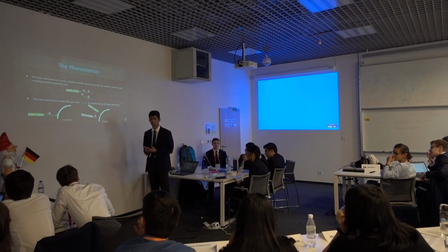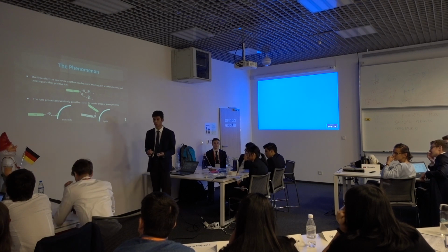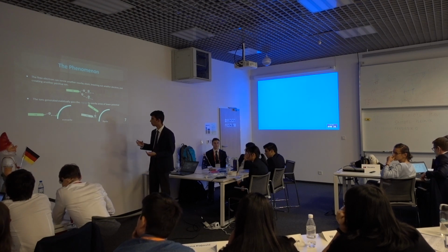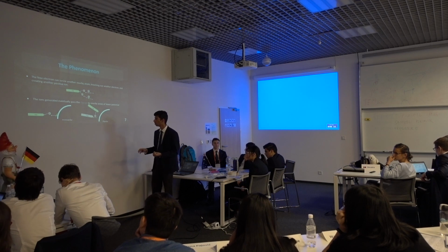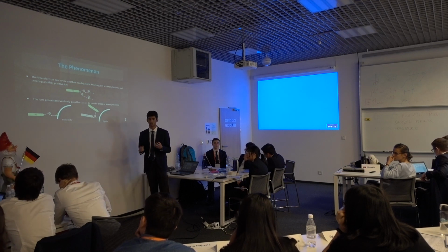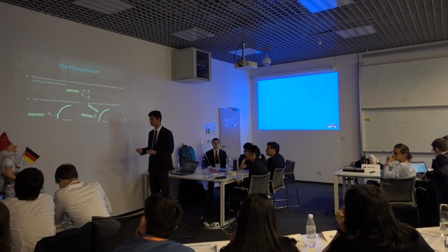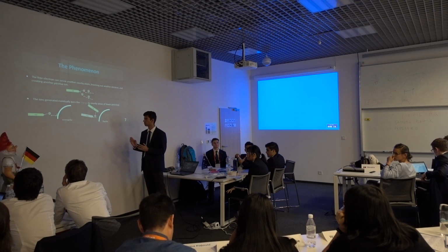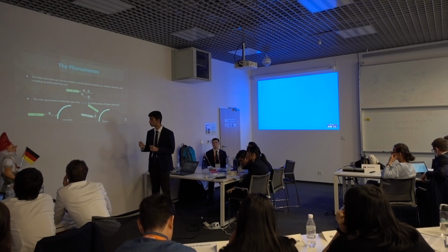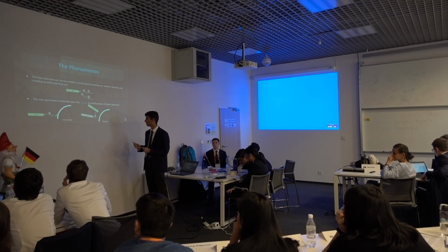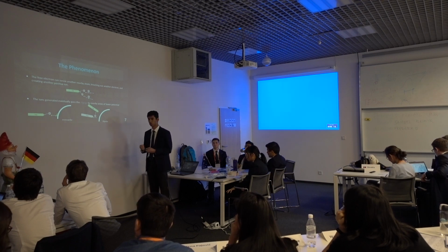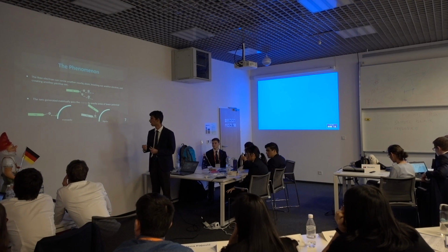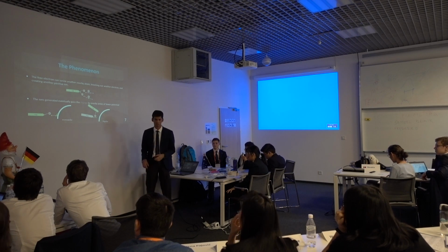In our case, this can be of two types: either monopolar, from a charged electrode onto a cylinder which is neutral, or dipolar, from a charged electrode to another charged electrode. And for our particular case, we want to maximize the monopolar corona discharge, and minimize the dipolar discharge, as this is essentially charge that is being lost and not going into our cylinder, which will not rotate.